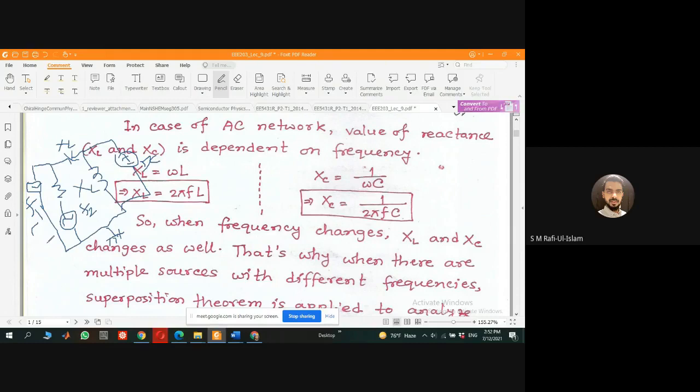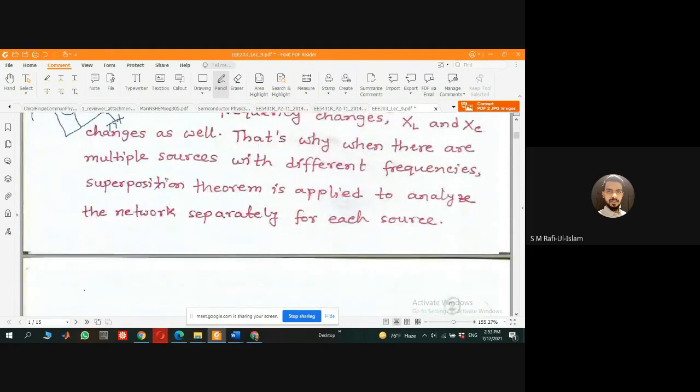If I have a DC and AC source at the same time, and I want to know the contribution of the DC source or the DC part, and the contribution of the AC part, then we can easily solve that with the superposition theorem. When we consider the DC source, all the other AC sources will be deactivated, so from that circuit configuration we can get the contribution coming from the DC. Later on we'll see some real examples.